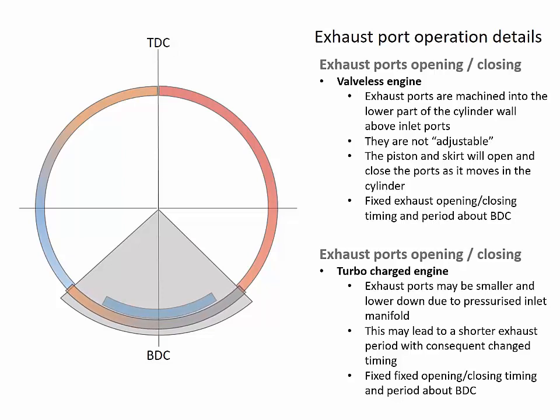In the turbocharged engine, similar to the inlet ports, the exhaust ports might be smaller as a result of pressurizing the air into the engine and forcing exhaust gases out. They could be having an effect on the timing by being smaller, so as to reduce the exhaust opening period, making more use of the compression and power strokes.